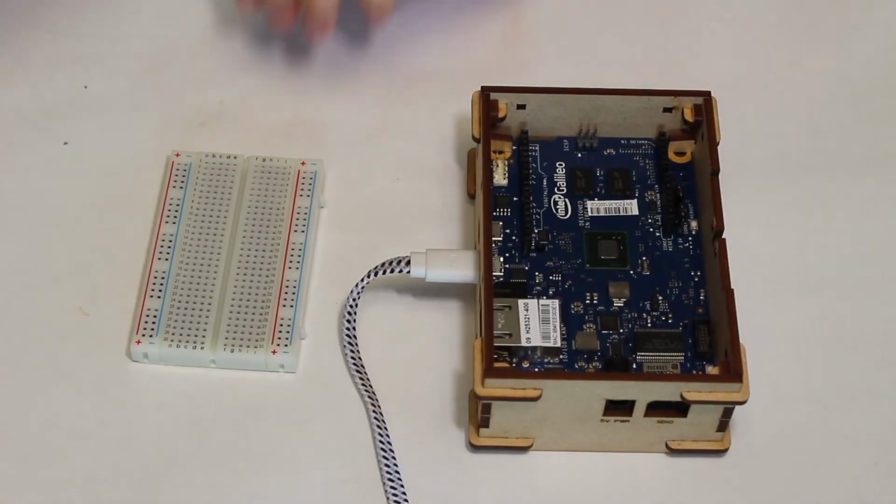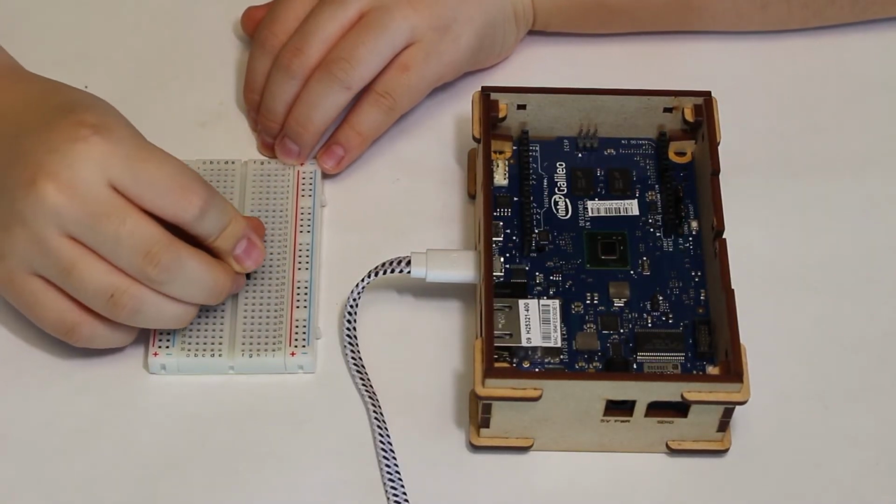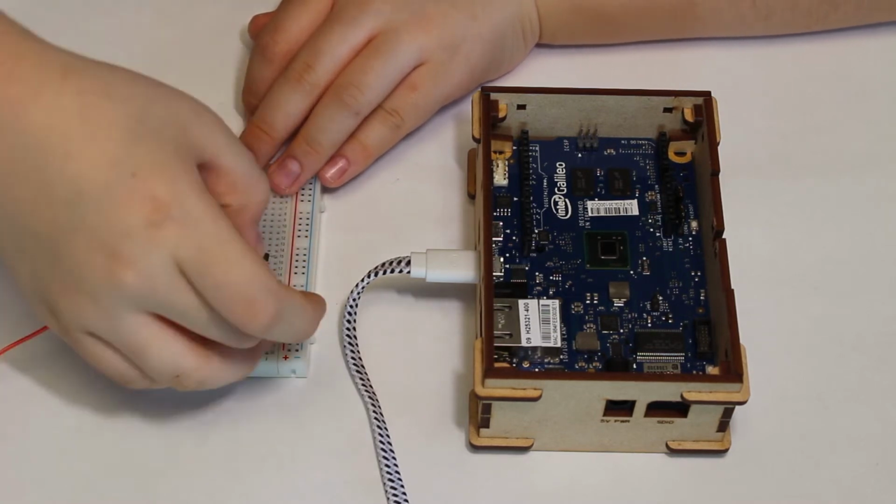An electronic sensor tells something about its environment by creating an electrical signal. This time we will experiment with the reaction of a light sensor to the surrounding environment, not controlled by a human. Galileo reacts to the degree of its surrounding brightness. Use the same jumper wires connected to the Galileo as they are. Now replace the potentiometer with a light sensor on the breadboard.